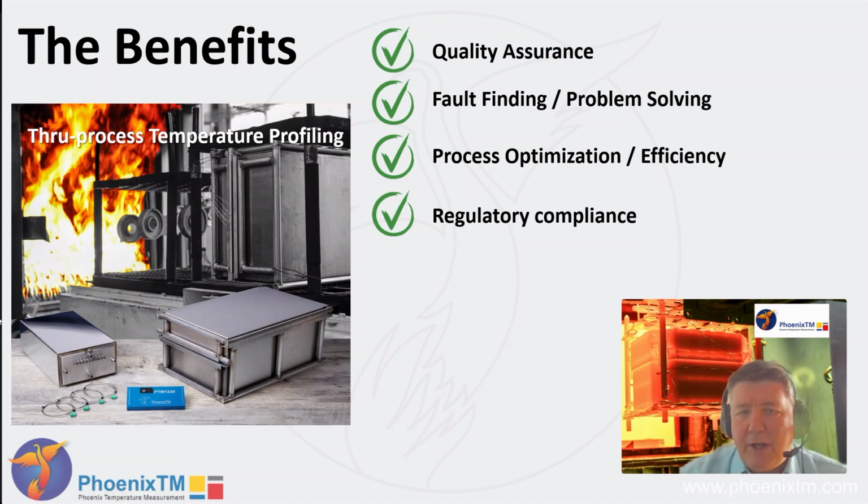Using the data from the profile, you can optimize your furnace both to improve productivity, throughput possibly, but also the efficiency of your furnace. As we all know these days, the cost of running a furnace can be very high. Therefore, everything you can do to improve the overall efficiency and fuel economy of that process has to be beneficial to your bottom line. Last but not least, you may be faced with quite significant regulatory compliance requirements, maybe working in the automotive industry where you're governed by CQI-9, or even the aerospace industry with AMS 2750. The software and the systems we provide allow you to achieve that compliance with efficiency and ease.